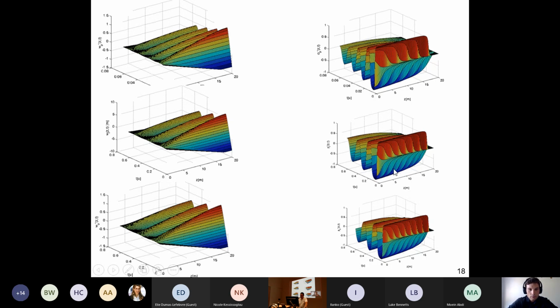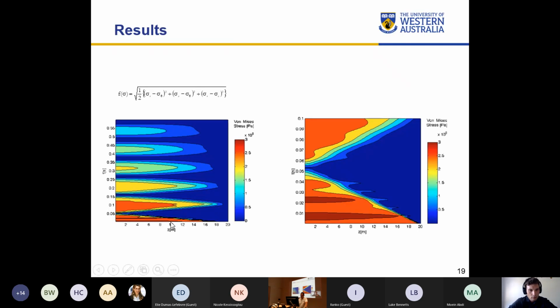You could notice that the frequency is higher in the pipe than in the fluids which are inside and outside, but also you will notice that the frequencies are pretty similar for the two fluids sitting inside and outside. We also tried to understand the integrity of the tube, so we used an equivalent stress, the von Mises equivalent stress, and this allowed us to see how the equivalent stress varies with time and space. You notice that this first half, or this area here, is the most critical. And it's really a moment after the experiment starts that you have the most critical stress occurring there. So failure may occur near the point where the pipe is being fixed. And that's where we needed to strengthen or do something about it.